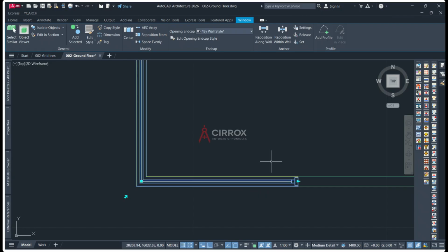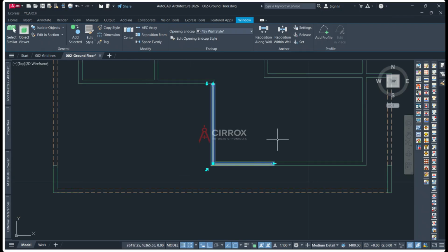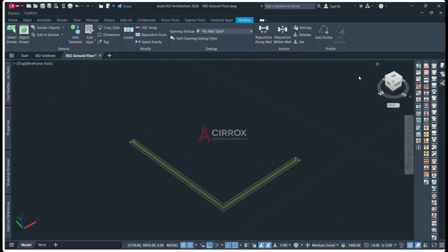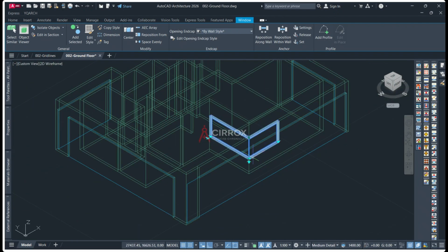It's going to be okay. And this is okay. And let me check the height, because I would like to make it so don't touch. So I'll go back to my properties and change the height to 3000.